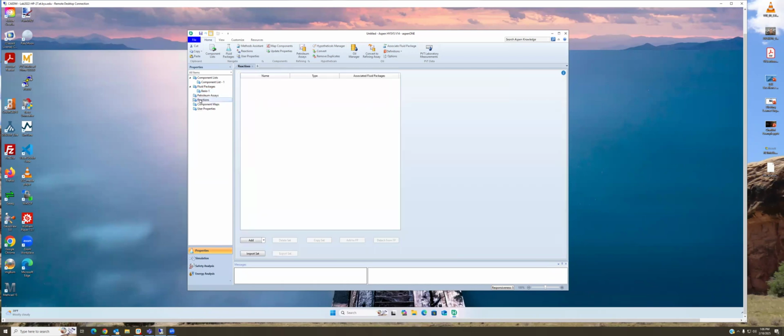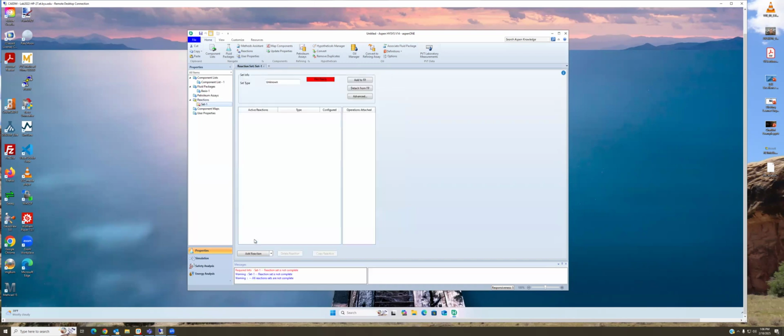Next thing we want to do is add the reactions that will occur in our process. Hysys and simulators in general allow you to put in individual reactions, and then these reactions are combined into reaction sets that are then connected to individual process units.